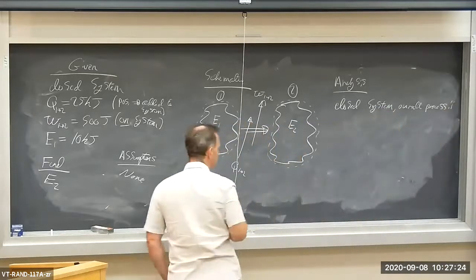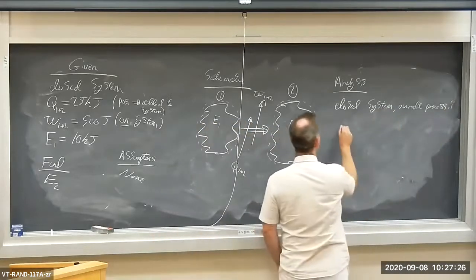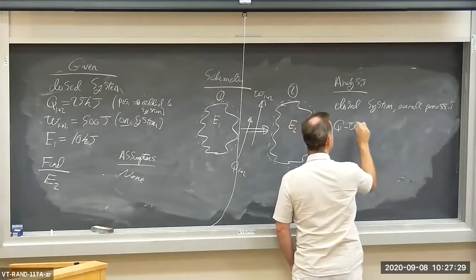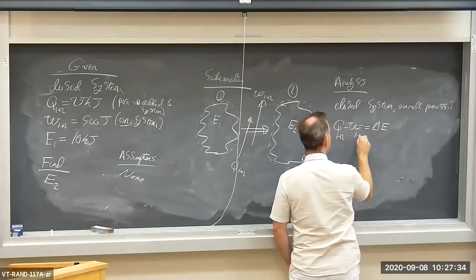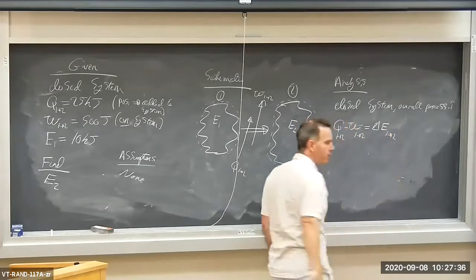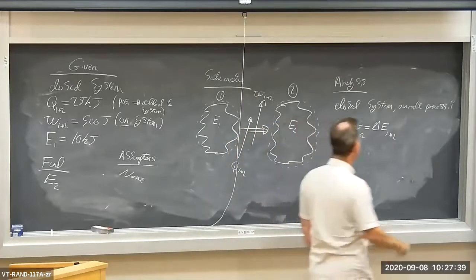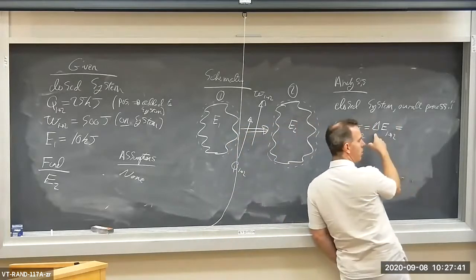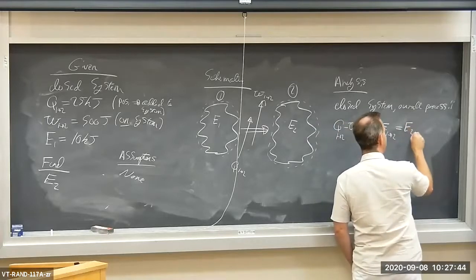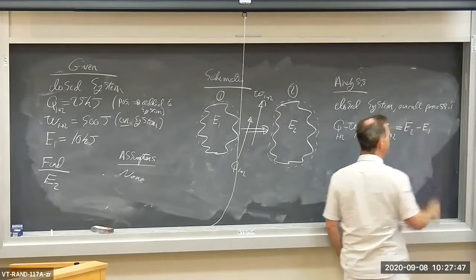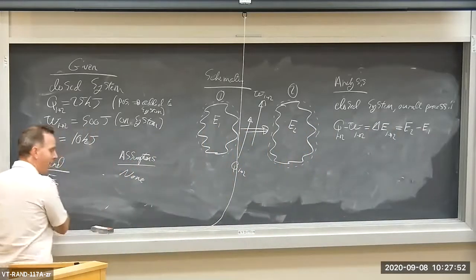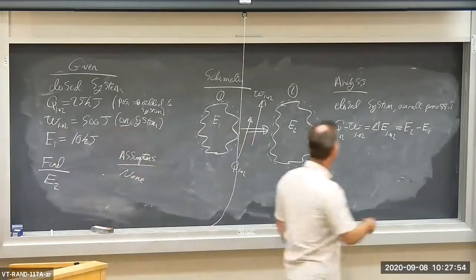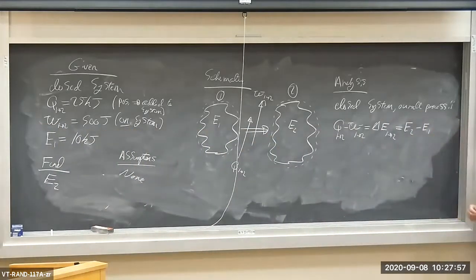Okay, let's write the E balance for the overall process closed system. Q minus W is equal to delta E. And this is all from state 1 to state 2. What's delta E from state 1 to state 2? That's going to be equal to, this is the change in total energy. So it's equal to the final energy E2 minus the initial energy E1. Note, E2 is what we're trying to find. So this is good news. I already see an E2 popping up in the equation. That's what we want to solve for.